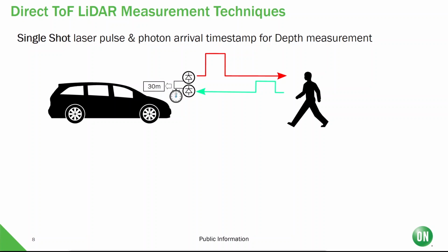In single shot mode, we would set the threshold of detection high enough to avoid triggering by ambient noise or ambient light. This means we would need a sufficiently high power level in the outgoing pulse so that it would meet our threshold of detection on the return pulse. Bear in mind, the return power will drop with the square of the distance traveled, and the return pulse power will also drop with the reflectivity of the target. So detection can become a challenge for long range and especially for light absorbing targets.